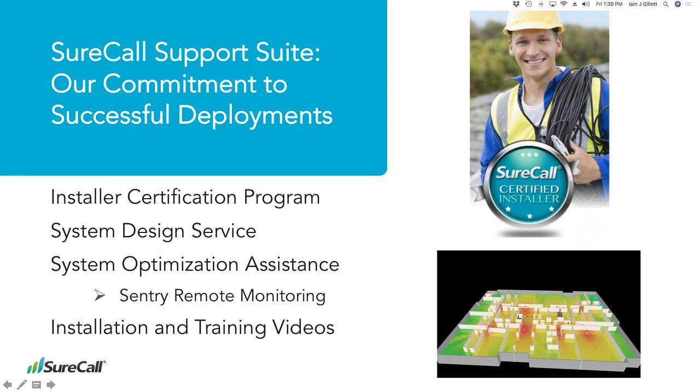So after the site survey, we have a questionnaire, a building recommendation form. It's 10 questions long, and it asks things like, what's the cell signal strength outside? We have a signal meter that the installer can take on the roof or where the outside antenna is going to be placed, and take readings in different spots for all 5 bands and notate those readings, right? Where are the strongest signals for all 5 bands?